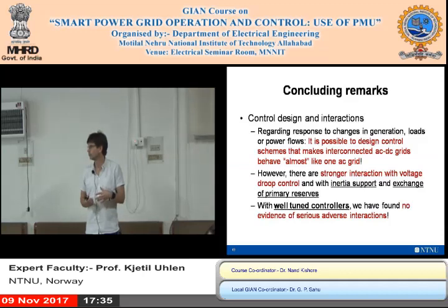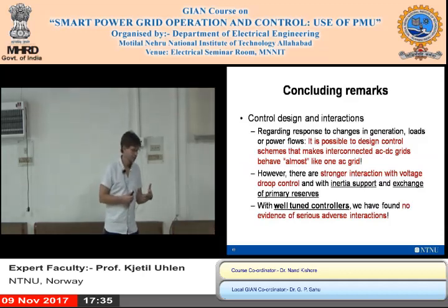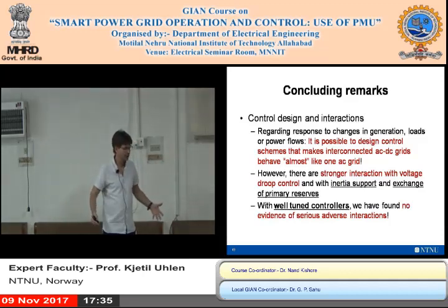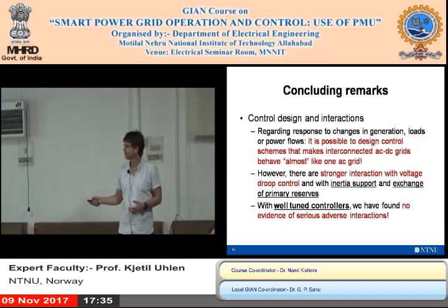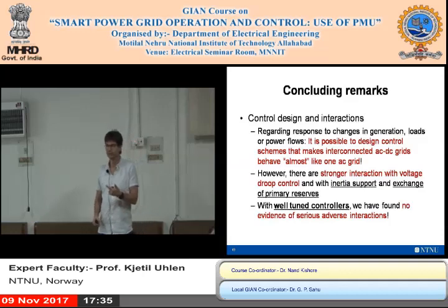And that is why I advocate looking into solutions where, instead of having huge AC interconnections, you could consider breaking AC interconnections up and having an overlying DC grid. I think that in countries like India, that could be an interesting solution, because it behaves like one interconnected grid, but it's less vulnerable to a total blackout.